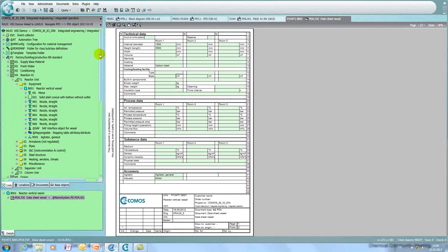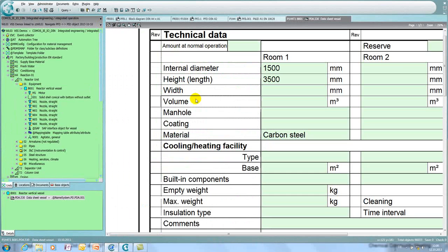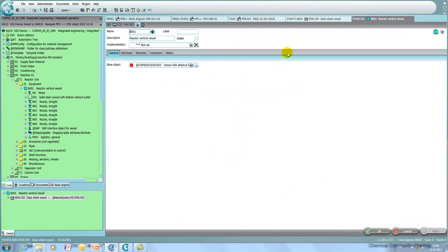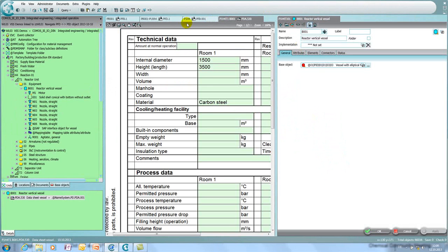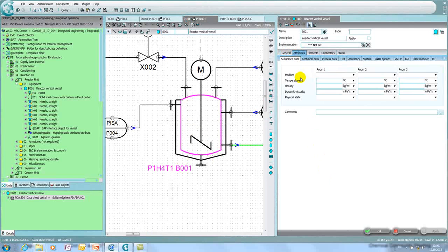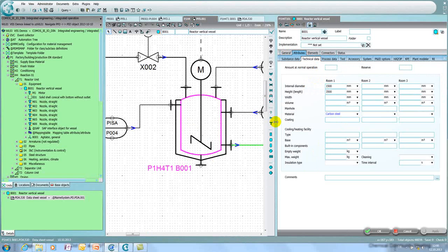And when we look into the material here on the upper left corner, then we see carbon steel. We also can open the properties of this component, which allow us to modify the drawing according to our needs. So when we look into the symbol and when we would like to have the material assigned to that symbol, we simply drag and drop it into the drawing as well.